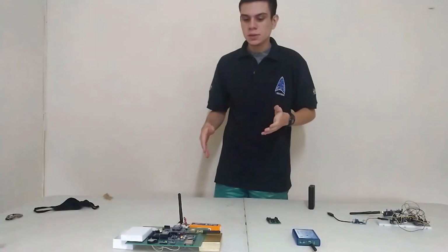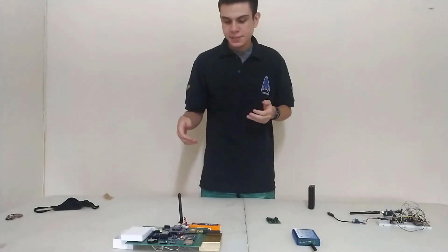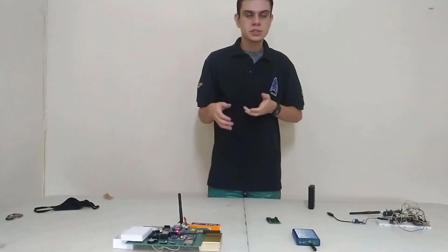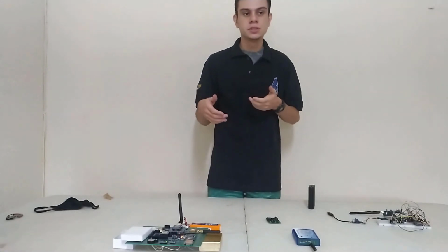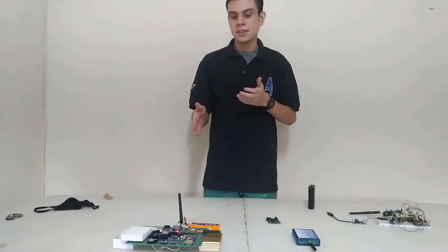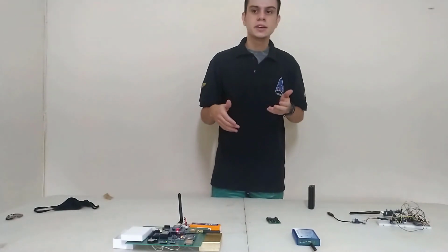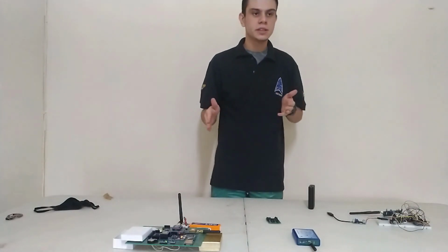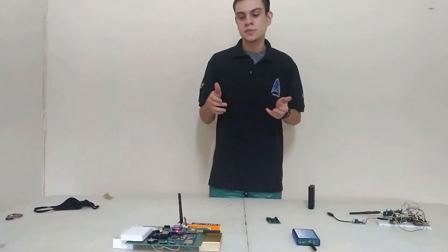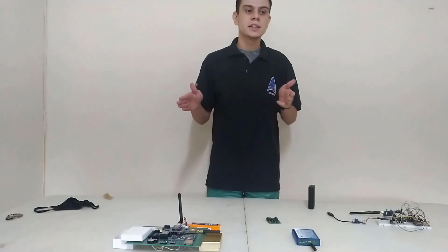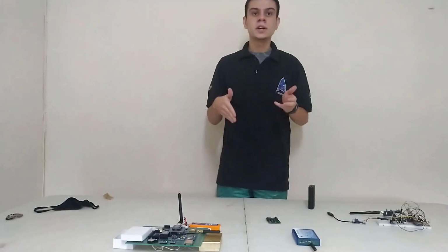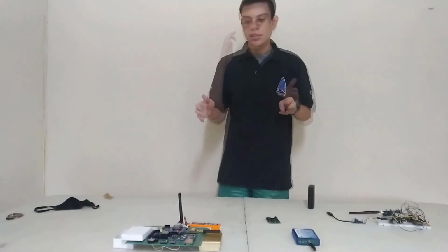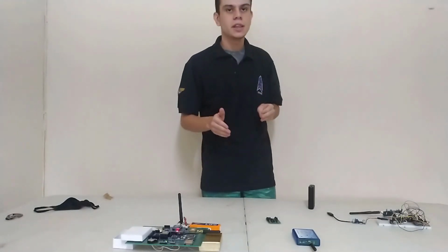So for this assembly, we conduct three types of tests. The first one is a short range test, which we do just like the one we just showed. We just check if this thing is sending the packages correctly and the other end is receiving them at really short range, like at maximum 100 meters or something like that, with a direct line of sight. We also do a long range test, in which we try to push it up to 3 kilometers the same way. And we do a battery life test.